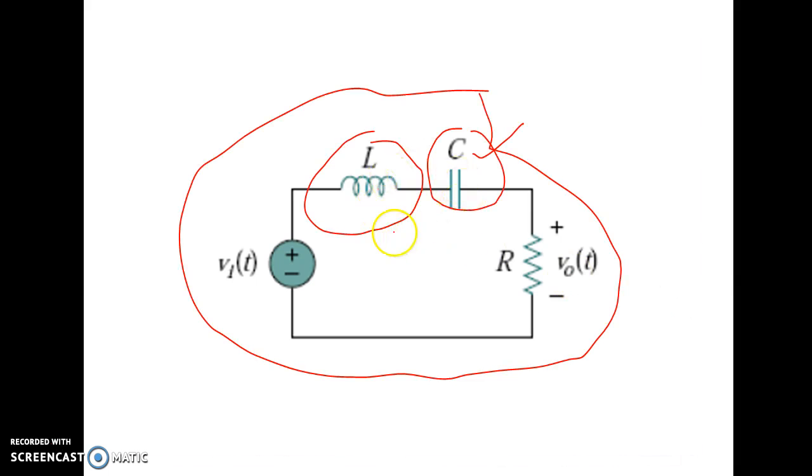See, from the circuit you will get an idea. When the current flowing through this circuit is in phase with the input voltage, then we say that the circuit is in resonance. This is possible when the circuit is purely resistive, that is when Z equals R, because in case of resistance only, the current flowing through the resistance is in phase with the input voltage.